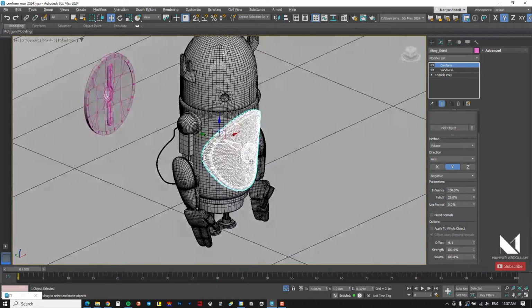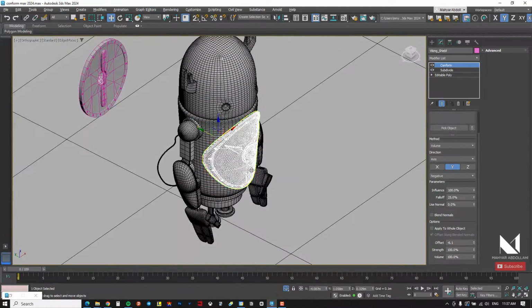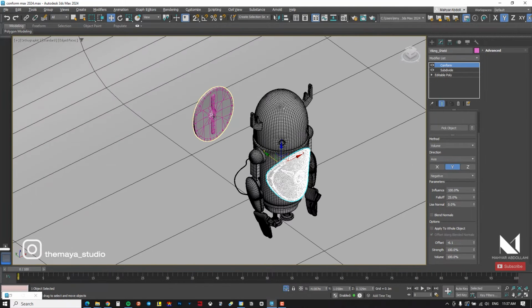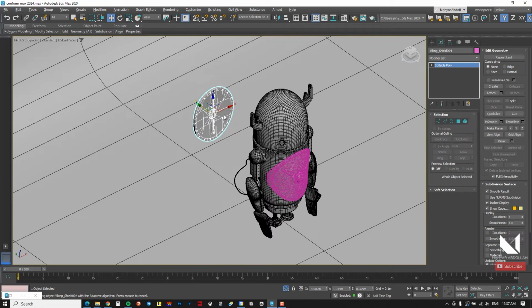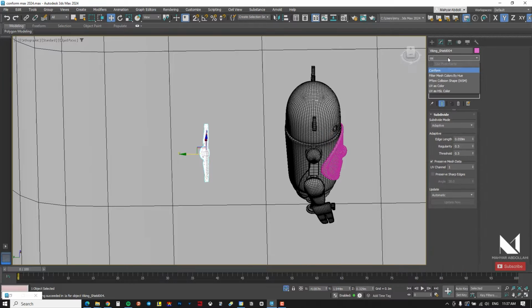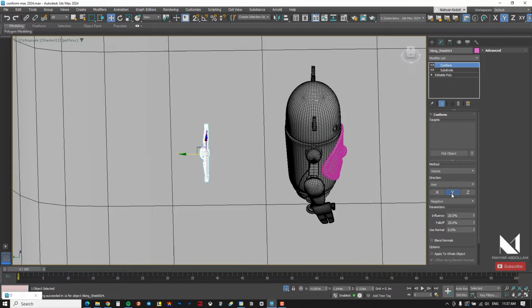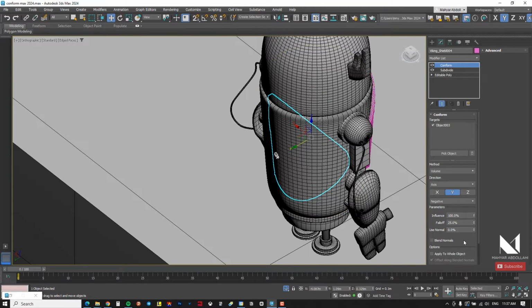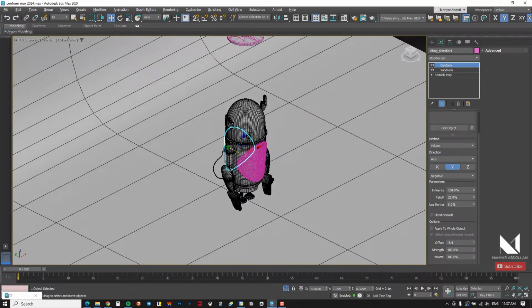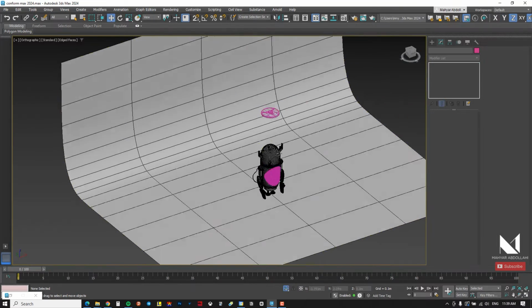Now it perfectly matches. I bring the copied subdivide from the previous part and paste it for the other shields. It takes the exact subdivide settings again. I apply the conform modifier. So knowing it needs to be on the y-axis with 100 influence, pick the object and bring the volume closer. So now it perfectly takes the shape of the second volume, and I apply the offset again to push it slightly backwards. So great. And finally, I follow the same step for the last volume.